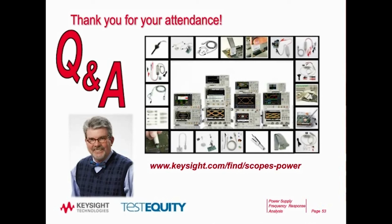Okay. In general, for power supply type measurements, is it better to use an active probe, non-powered, versus a passive probe? That depends. If you need high sensitivity, you're measuring millivolt kind of stuff, you have to use a one-to-one probe. And if you use a passive one-to-one probe, it's got low bandwidth. An active one-to-one probe has high bandwidth. So it depends on if you need the higher bandwidth.